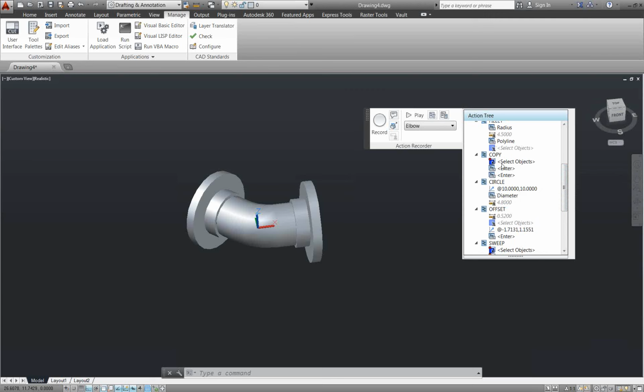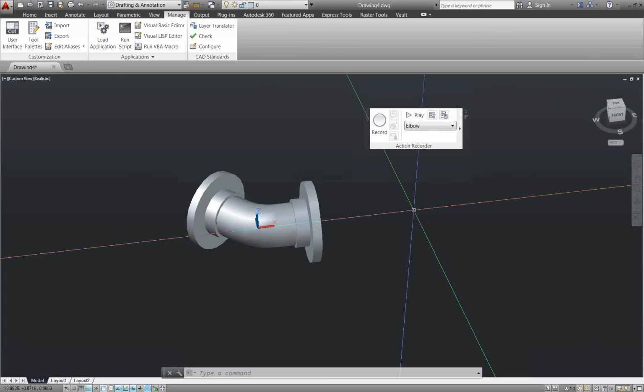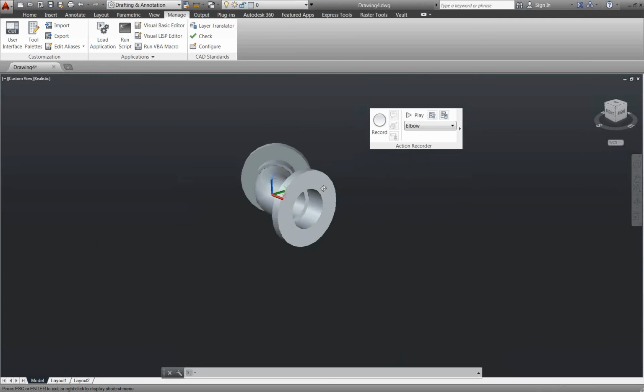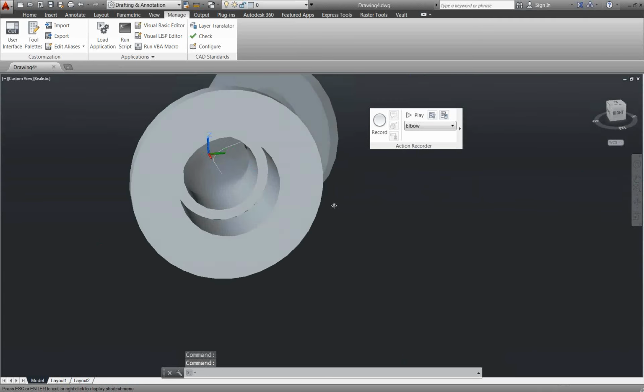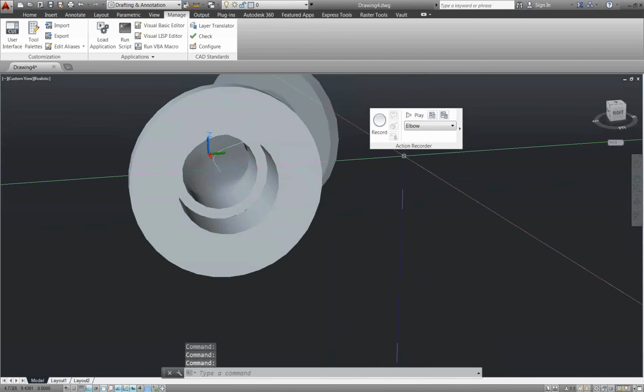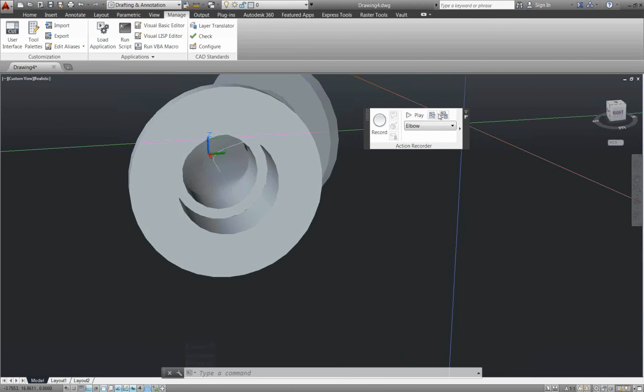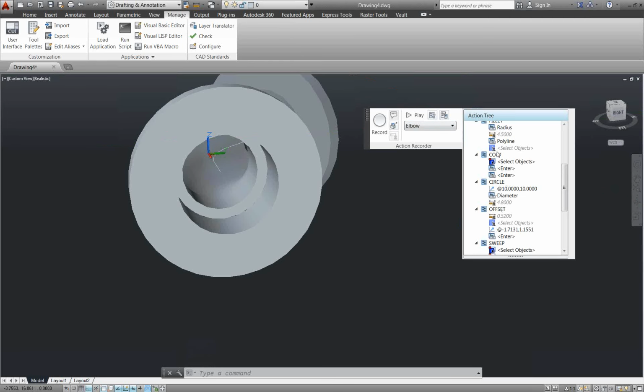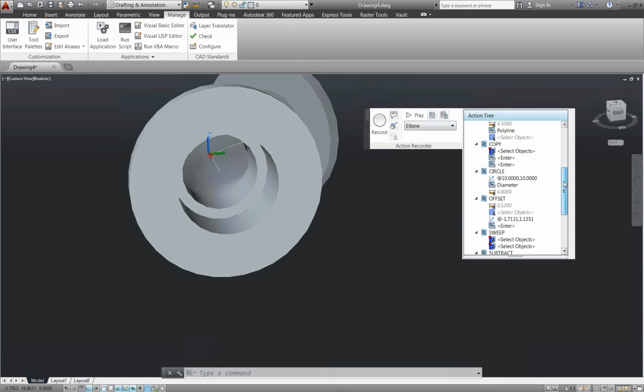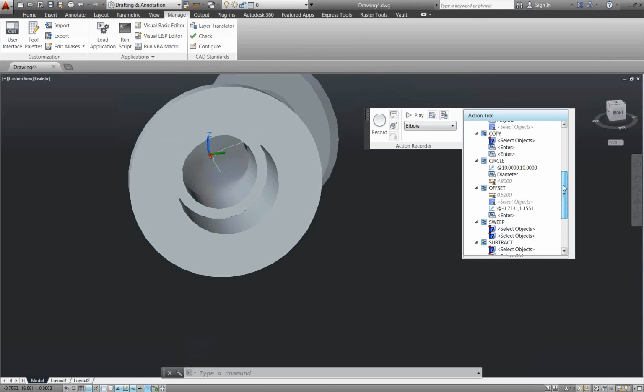It actually created a copy of the polyline. You might notice in here, if you've ever done any of this, there's that polyline running right down the center of the pipe. When you use the loft command, it actually deletes your polyline as your path. So what Brian's done in this case is copied the polyline so that we get a polyline left over.